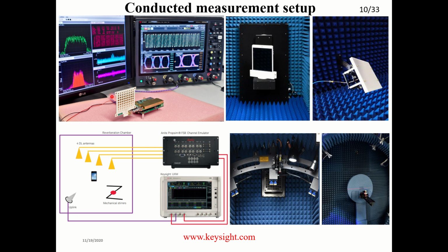So these are some of the measurement setups you can see here. You are connecting your device and then verifying and validating everything. Sometimes you have to keep your mobile in a shielded box, otherwise it may be due to the environment that it might cause some problem. We may not be sure whether it's a real UE problem or an environment problem, because in the lab we will have a lot of equipment. Due to that interference, it may cause some issues, so that's why a shielded box is preferable.